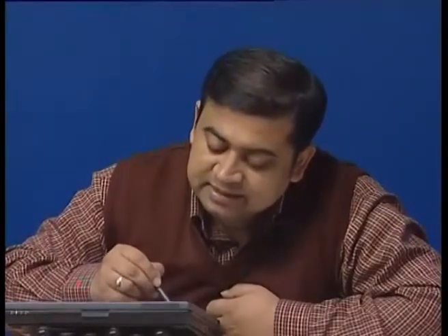Okay, and then once this is done, you can remove the ports along with the PDMS with the channel-like structures, and then plasma bond it over this lower plain glass slide. And that would give you a device looking like this. So you have these small ports here on all four sides, and this is the crisscross channel that you can see. These are real-time optical micrographs of such devices.